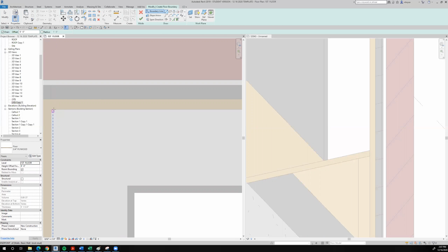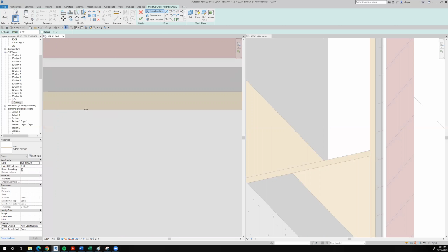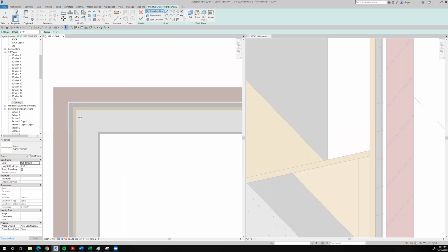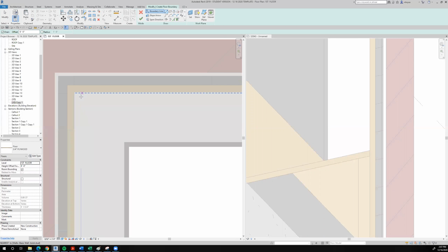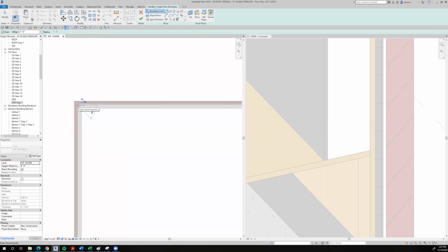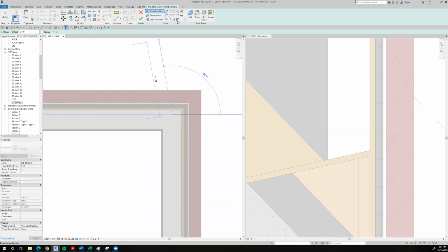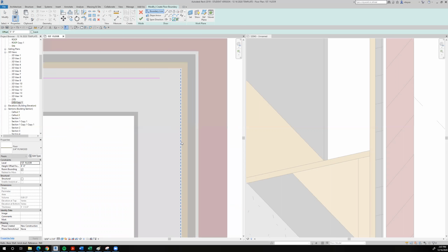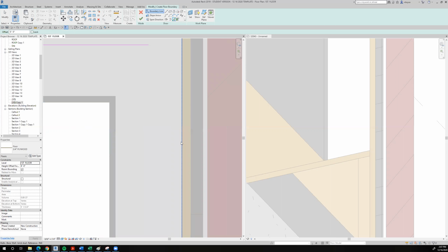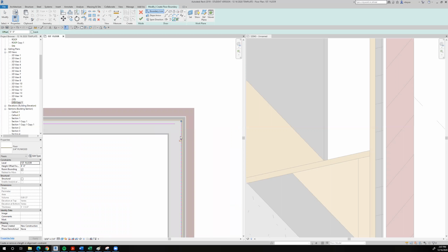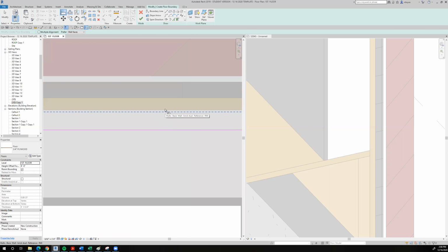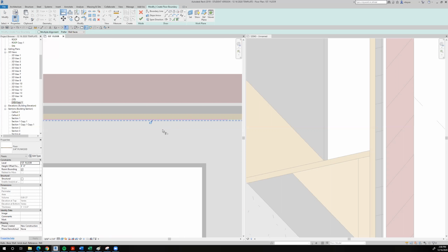Tab, tab, tab, tab, tab, tab, until that wall is actually highlighted. So we're waiting for that wall to be highlighted, and it's not. It's not letting me pick that. So I'll just draw it right here. I'll come all the way across to here, and then I'm going to pick this wall. Let's see if it'll let me do it now. See, I hit the tab key until the portion that I want is highlighted. And I'm going to quickly go back and fix this by aligning it to, hopefully I can get that. Yep, there it is. I'm aligning it right to there.